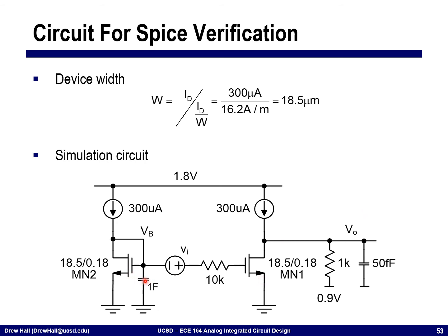I'm adding an extremely large capacitance here of 1 farad in order to decouple this and not contribute any poles or any frequency response from the bias circuit itself.